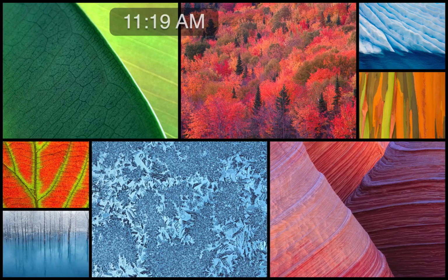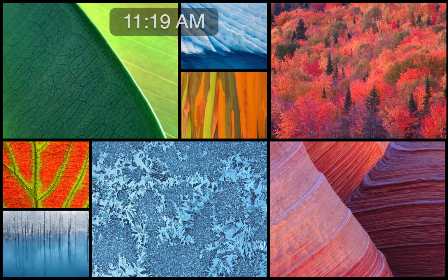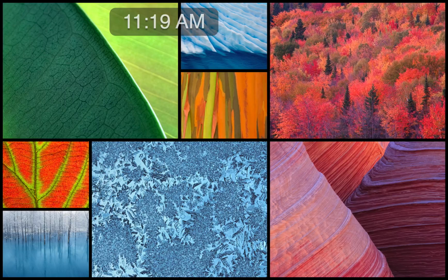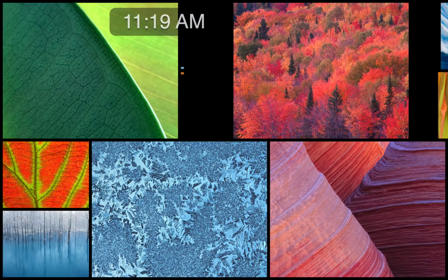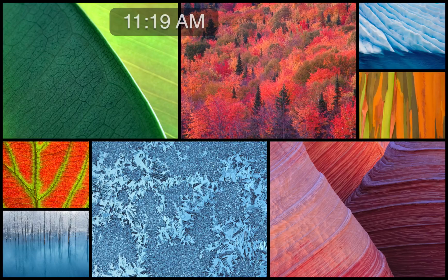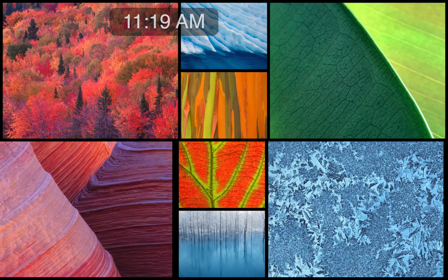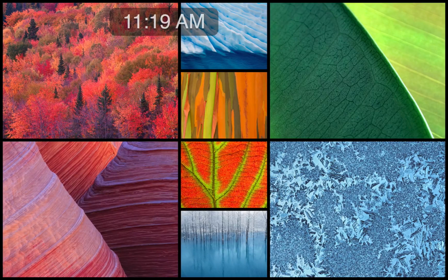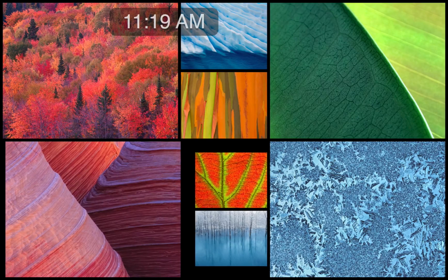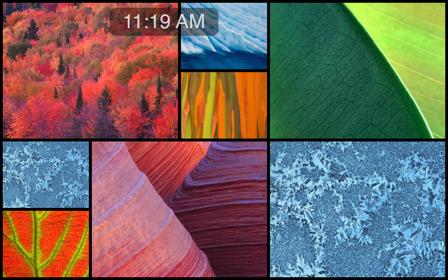Okay, so then this guy is now, we're going to click on this and change it to a skyline 4x4, and we're going to align it with this reference line and align it with this grid line, okay? And then the next thing I want to do is align this reference line here with this core, okay? So all my stuff is lining up the way I would build it.